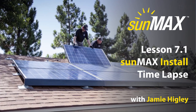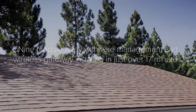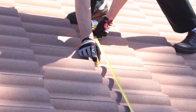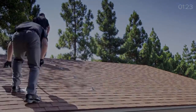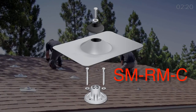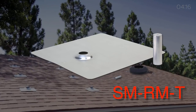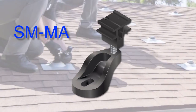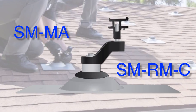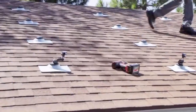Lesson 7.1 SunMax Install Time-Lapse. The following video depicts a 9-module array roof installation from start to finish. After measuring and marking rafters for install, compartmentalize tasks in a team as you drill, bolt, and fit the mounts and flashing to the rooftop. An additional flashing piece is used with tile rooftops. With the mounts securely in place, insert the first row of mounting assemblies, then tie a leveling string at both ends to adjust the height of the assemblies until they are the same across each row.